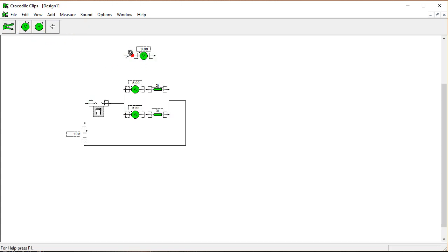In order to measure the voltage, we can use the voltmeter, the one we were using before. Just one is gonna be okay, because we just need to measure one voltage here, the one before the resistors, and the one after the resistors. So we can see that the voltage that is being generated by the battery is 10, and the voltage that is being consumed by these resistors is 10 as well. Everything that is being produced here is being consumed in both of the resistors. But the current we are generating here is 8.33 milliamps, and that current is being shared by this one and by this one. So this one is getting 5 milliamps and this one is getting 3.33 milliamps.